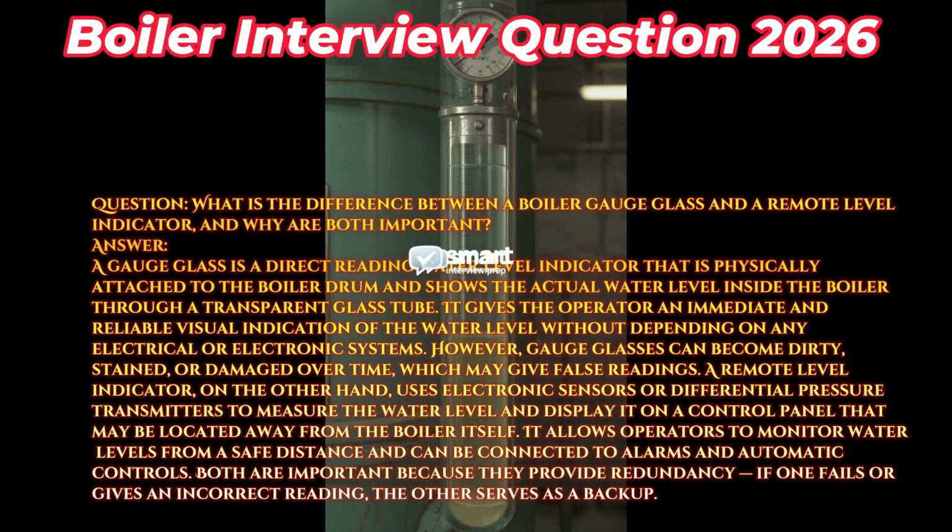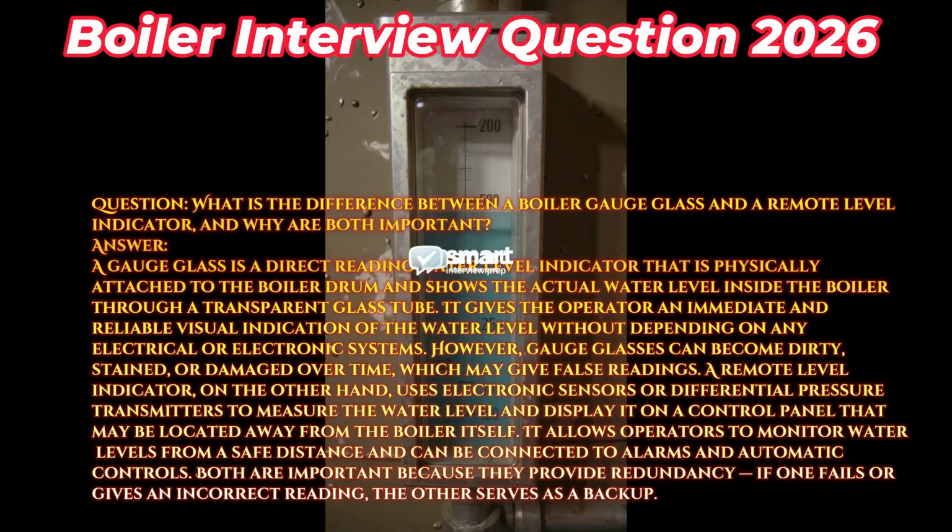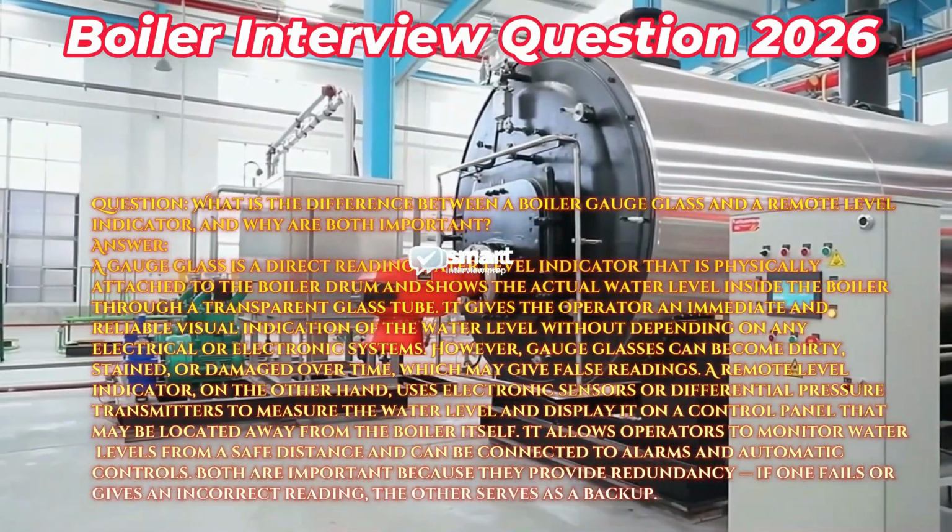Question: what is the difference between a boiler gauge glass and a remote level indicator, and why are both important? Answer: a gauge glass is a direct reading water level indicator that is physically attached to the boiler drum and shows the actual water level inside the boiler through a transparent glass tube.